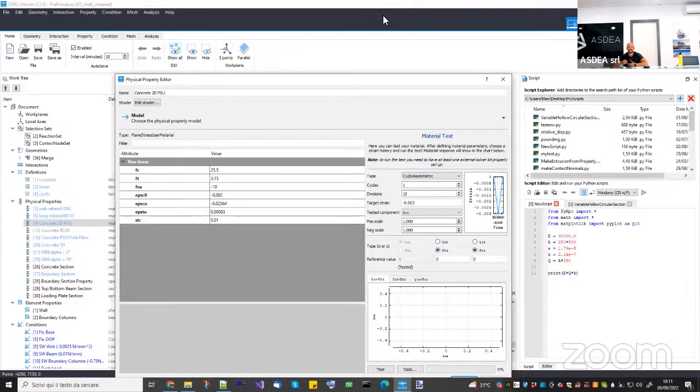What you cannot represent is a nonlinear transverse shear, but you are only interested in that if you have very thick plates, which I don't think is the case for the typical case in reinforced concrete, or if you want to model, for example, punching shear. Of course, if you want to model punching shear, you need a model that can capture nonlinear transverse shear.